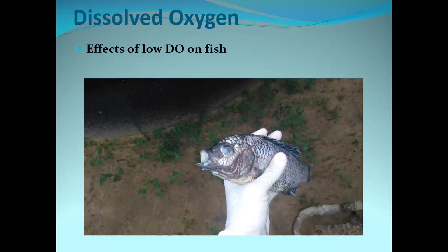So at nighttime, what happened is that because there was so much algae, they were utilizing all the oxygen from the system, leaving very little for the fish. And the fishes were suffering at nighttime from a lack of dissolved oxygen, and they basically piped and died. Every night was a whole set of fish mortalities he was getting, until I went to troubleshoot and there were a couple of things I recommended to him, increasing aeration and all these things to help with the dissolved oxygen problem.